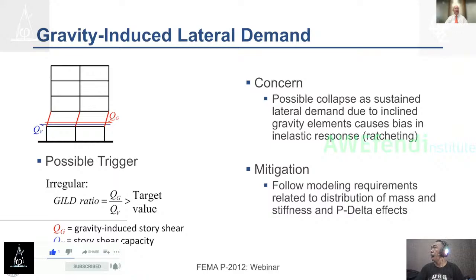In the case of this simple cartoon, all of the weight above the red columns is at one location in plan, and that same force has to be at a different location in plan below. And so there's a horizontal shear that resolves into the system. And that shear has to be resolved in the lateral system because that's the source of lateral strength and stiffness. So even if there's a single sloping column, there are thrusts induced in the system that should be considered. So that's the behavior, that's the background of why it's a concern.